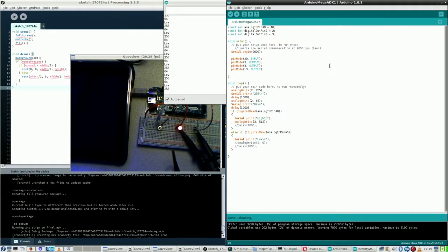A little bit change of setup. What I have changed is now that when I press the button, I do not write to port 2 but to port 3. So I have added here digital out pin 3.